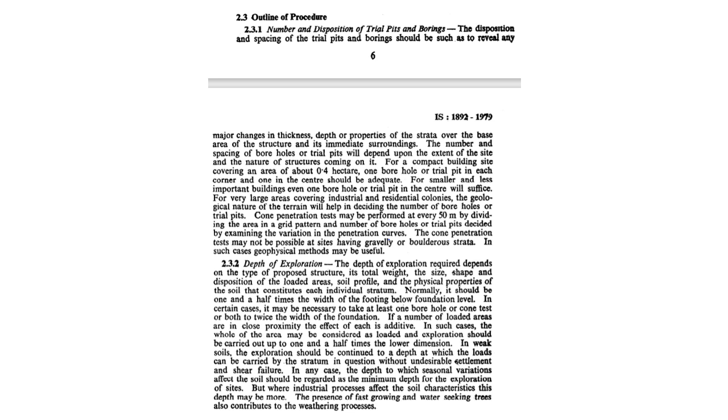Okay, or in the case of industrial structures, you might be having heavy machine foundations as well, right? There will be heavy machinery involved. So beneath that, they are also heavily loaded structures within your building. So it will be ideal to take one borehole beneath those heavily loaded machines as well. Okay, when it comes to the construction of industrial plants or structures.